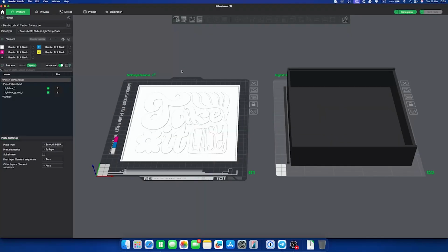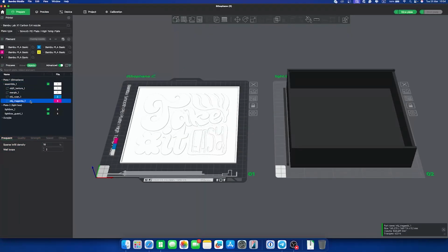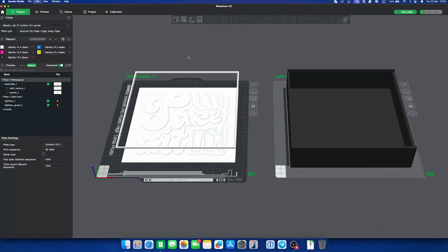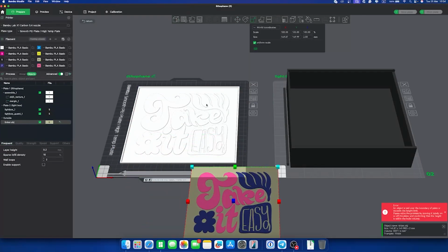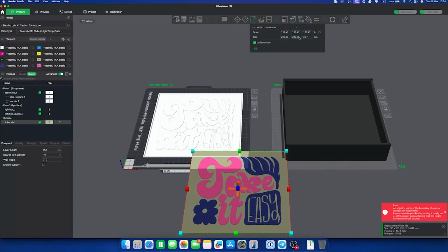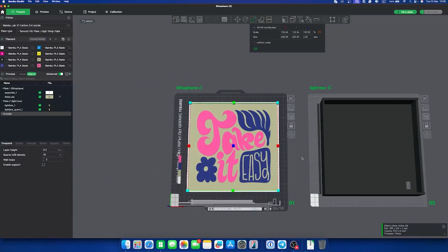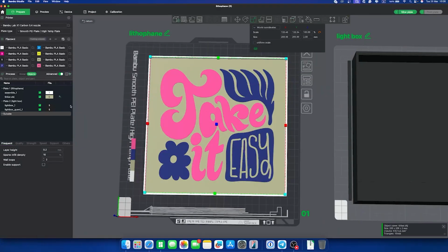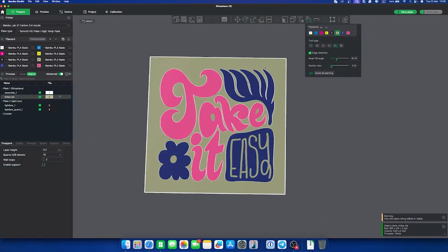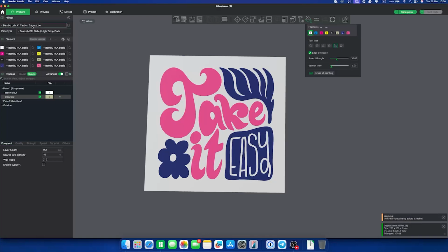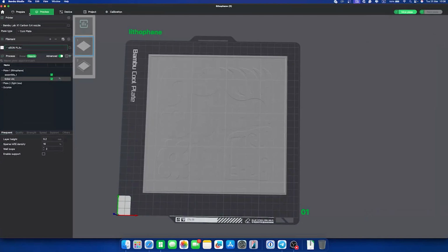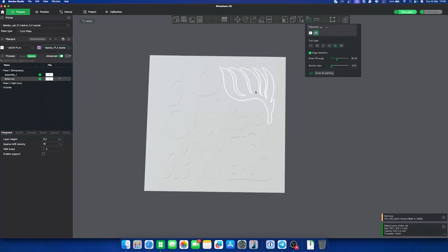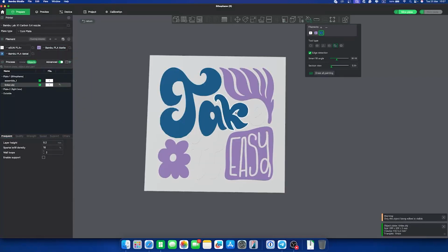First, I open the lamp base file in the slicer and import the illustration model as well. Next, I proceed directly to configuring the printing settings. Initially, I select my printer, Bambu Lab X1C, with a 0.4 mm nozzle. Then, I select the plate that I will be using and update the model's colors according to my previously chosen filaments. Additionally, I always increase the nozzle temperature for the first layer, ensuring a more stable and high-quality foundation.